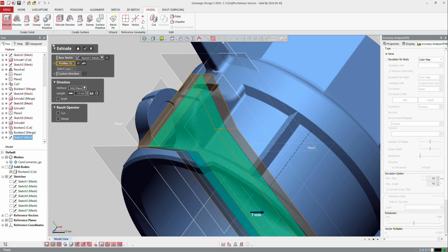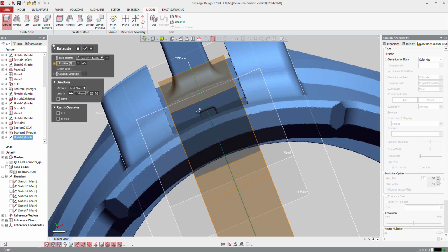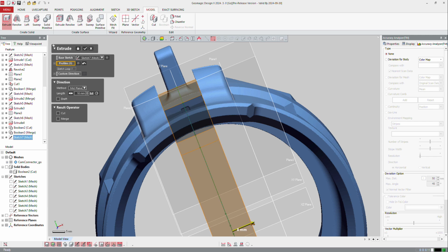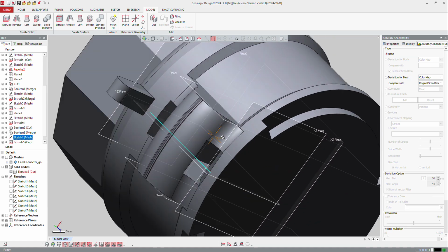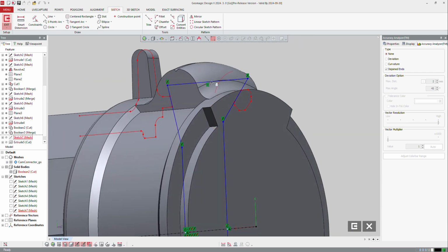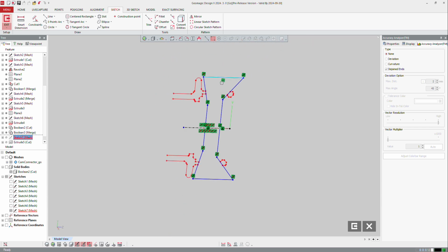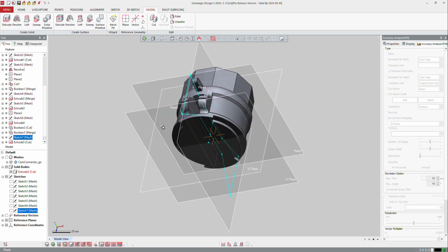And I have to make sure that I remove that. So if it's not right, I can always go back and modify my sketch. So here I'm going to increase the distance a little bit, so 8, and cut. All right, so of course, if I look there, it's not right because I didn't go far enough. So I can always go back to my sketch and maybe here pull it. So you see it pulls it on both sides, and exit. And as you can see, everything has been updated and I don't touch the side.